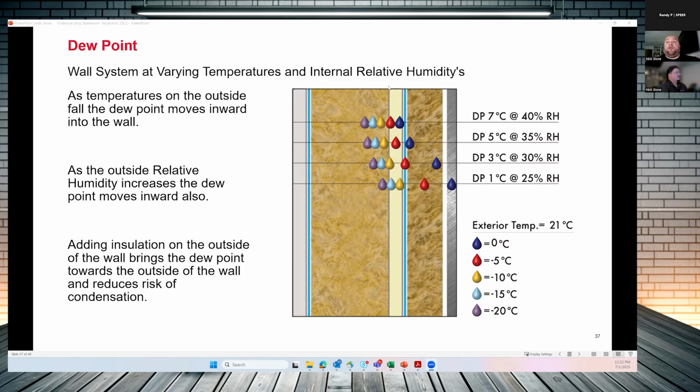But now we have materials that do not manage moisture from the wood perspective quite as well. So by keeping our condensation out of our wall assembly and keeping it out here, it's going to keep the system dry, keep this draining, keep this nice and dry in the cavity, which is going to cause less issues as those buildings age.